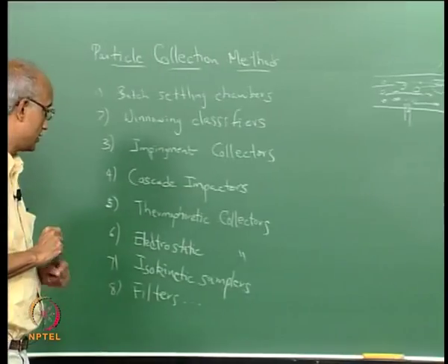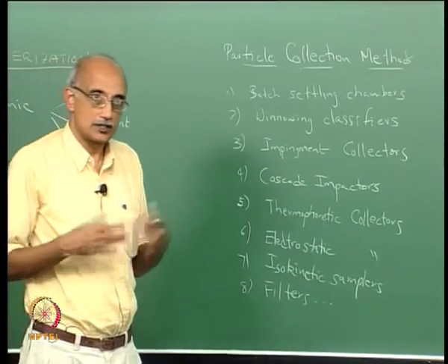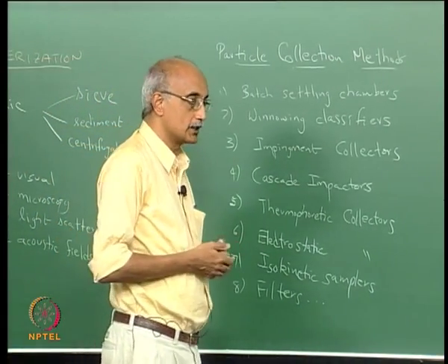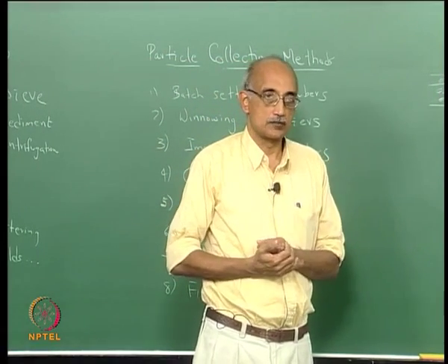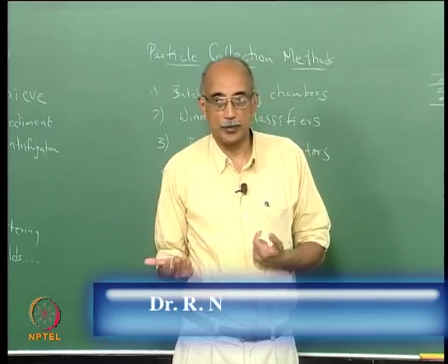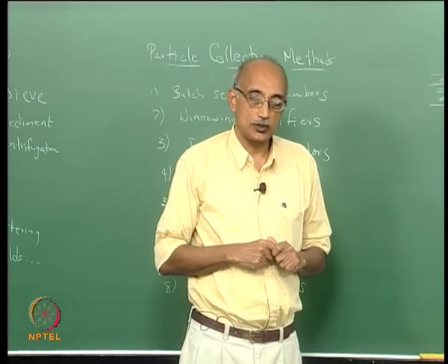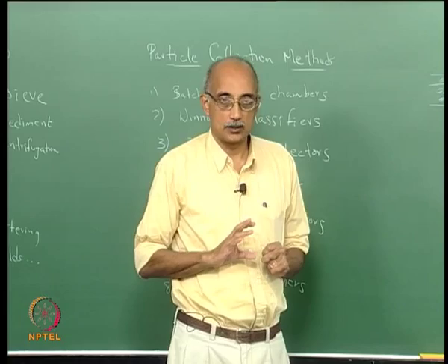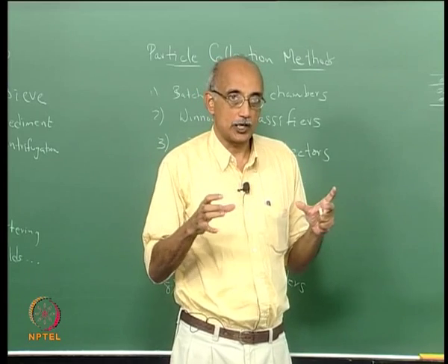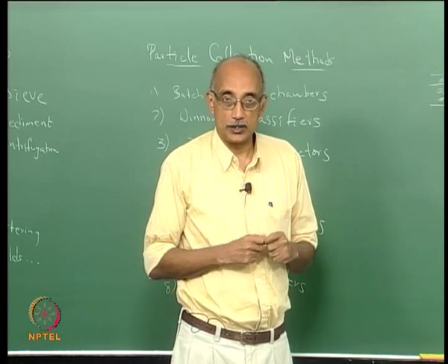The last technique here is filters, and this is something I am sure you are all very familiar with. We always use filters to collect particles for analysis. There are two types of filters, membrane filters and fibrous filters. The mechanisms involved in filtering particles are very different in these two types of filters, and therefore the size ranges that you can collect with the two types of filters are also very different.